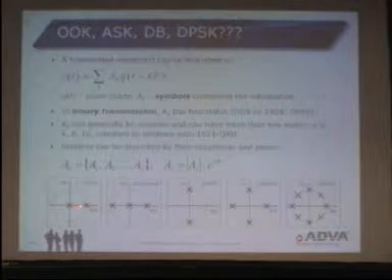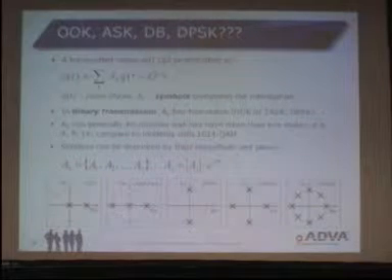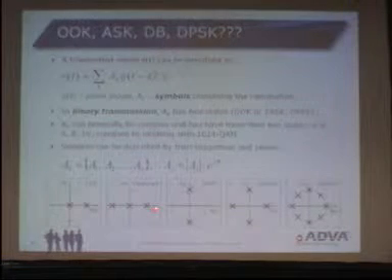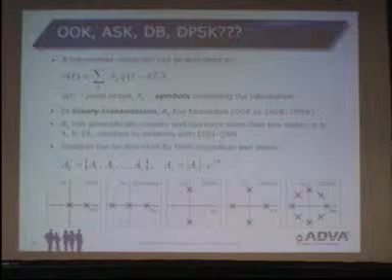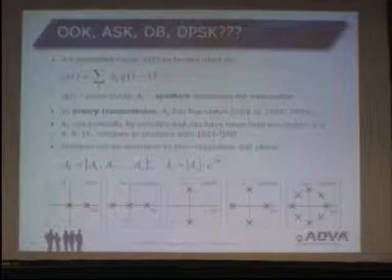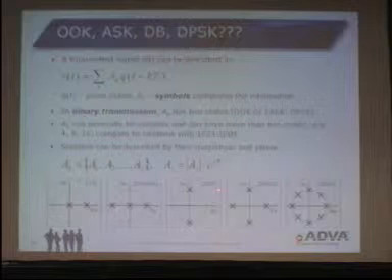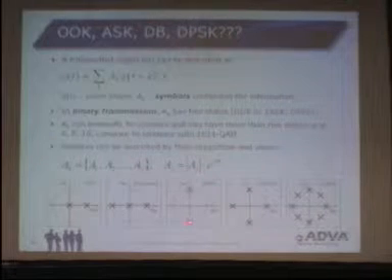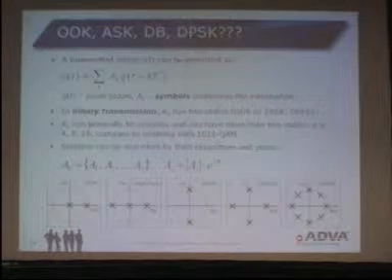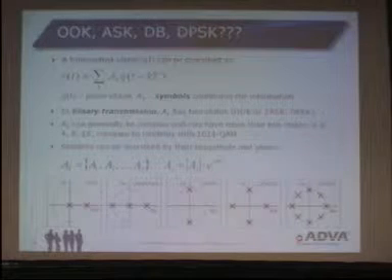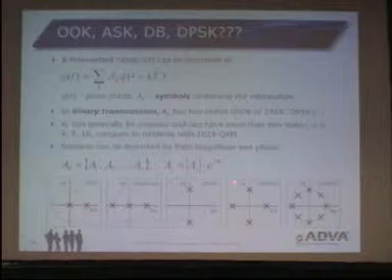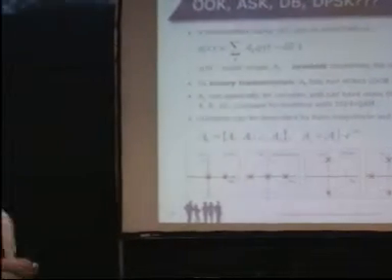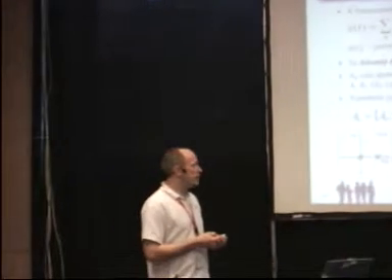And the other candidates that we are talking about now mainly are these. It's not all of them, but some of them, where duo binary is a ternary modulation scheme. I think it is well known from power line communications as well. Differential phase shift keying is binary as well, but both states are transmitted using power, and the information is encoded into the phase. And it has to be differential phase shift keying because in optics we can't directly detect phase.